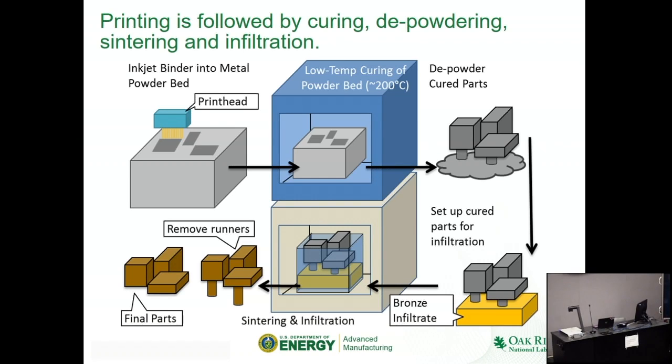And so what happens now is that we have to create material that is like an alloy. This could be any type of metal that has a higher melting point than bronze, because bronze is what we currently use for infiltration. We set bronze up underneath the parts that we actually want. During the sintering step, this bronze is wicked in through capillary forces, or capillary action, and fills that 40% void space in the high temperature furnace.